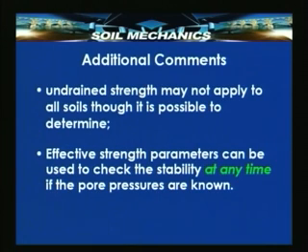It is not necessary that we need to use only the total stress parameters for a situation where the UU test results are required. If we know the pore pressures at any point of time, if pore pressures are measured in the test, then always the effective strength parameters can be calculated and they can be applied for computing the stability of the dam at any stage, not necessarily at any particular stage.